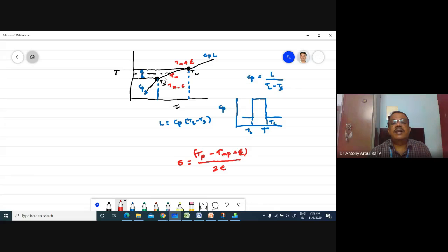So now if the temperature is somewhere here, for example, you think that the solidus temperature is 30 degrees and the liquidus temperature is 32 degrees. You may be wondering how it is possible. Yes, it is possible. There are phase change materials at low temperature which will be melting and solidifying at low temperature. There are materials available which change phase at 25 degrees centigrade and also at 30 degrees centigrade. A wide temperature range is possible.